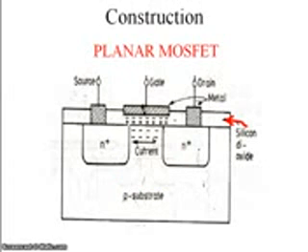Now this insulating layer is etched in order to embed two metallic source and drain terminals. Here note that the N+ regions make contact with the source and drain terminals. A layer of metal is also deposited on this silicon dioxide layer so as to form the gate of the MOSFET in between the source and drain terminals.